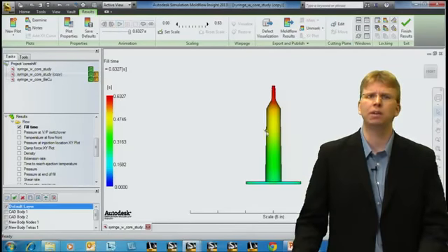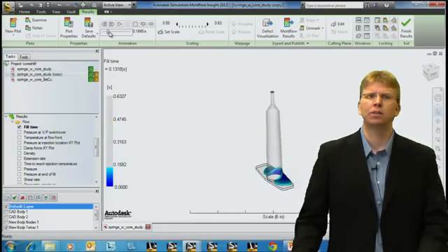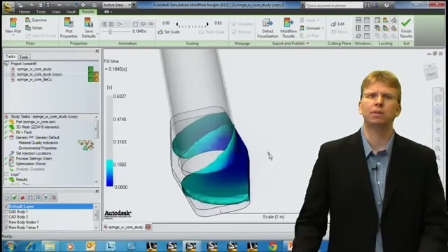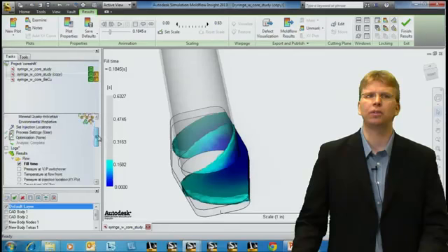It looked pretty even except for the beginning. So I'm going to just back it up to take a look at that. So as we inject on one side of the part, we can look in or zoom up and see that half of this core, or this side of the core, is seeing pressure, whereas this side is not. So that's probably going to cause the shift in the core itself and change the thickness on the top. So we'll investigate that a little further.